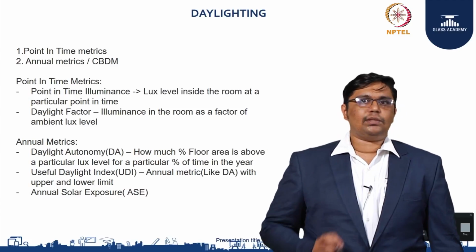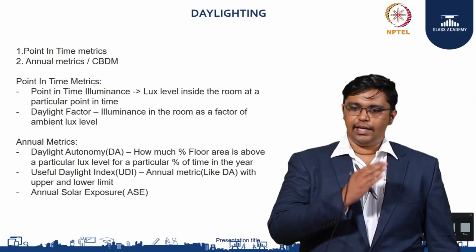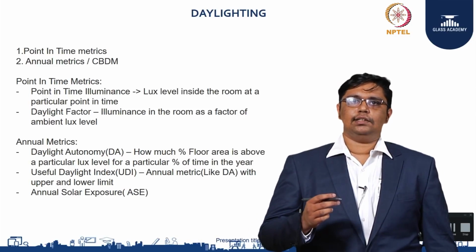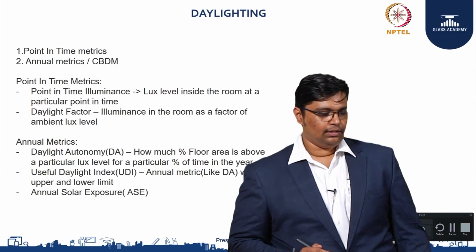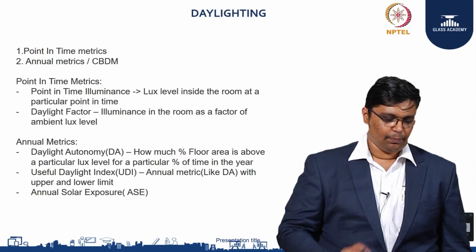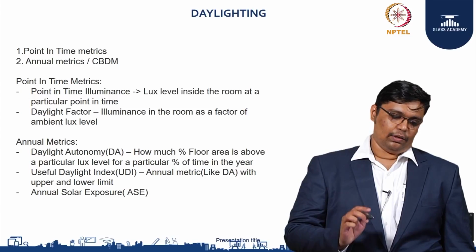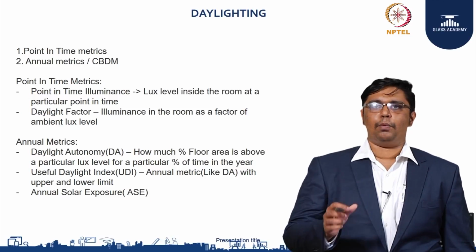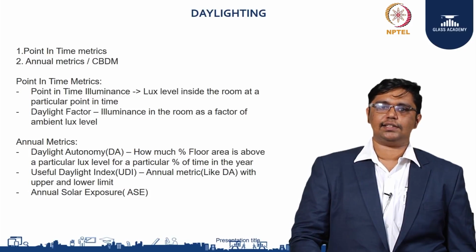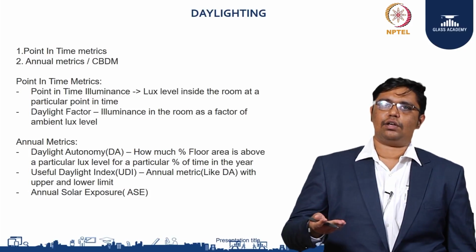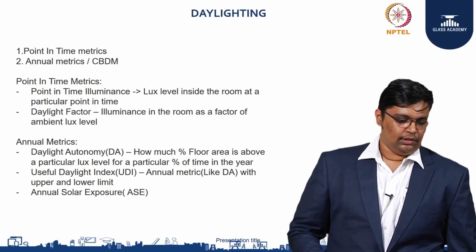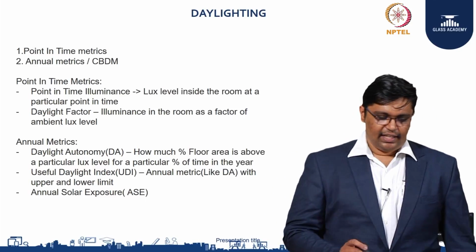And the annual metrics, which consider the entire year in your simulation, and it lets you know how much daylight will be coming inside. So let us see one by one. First, in point in time metrics, one typical metric that is used often is your point in time illuminance, where you will understand how much is the lux level in your floor plate or your working plane at a particular point in time. And next is your daylight factor.